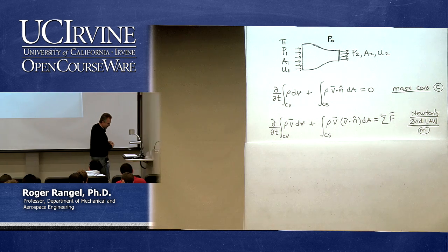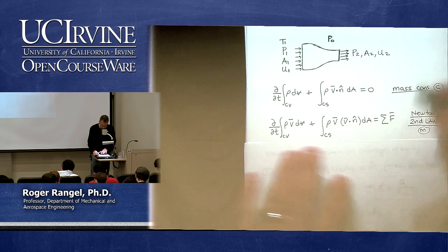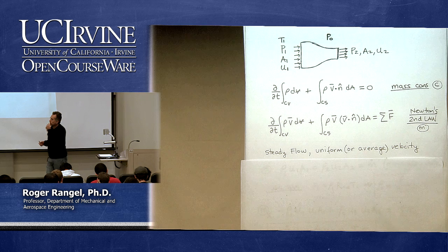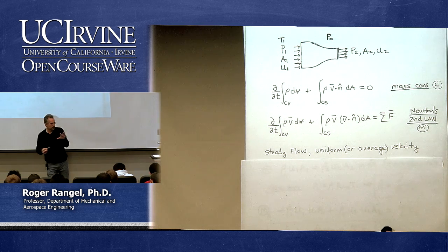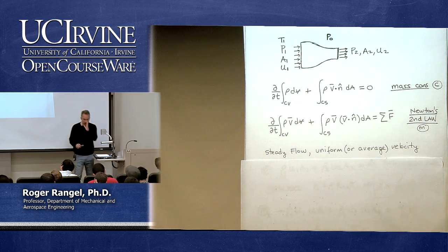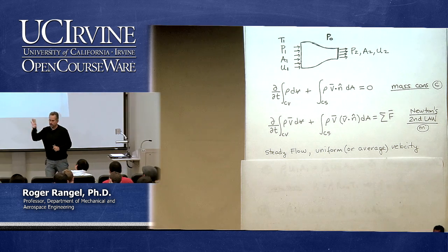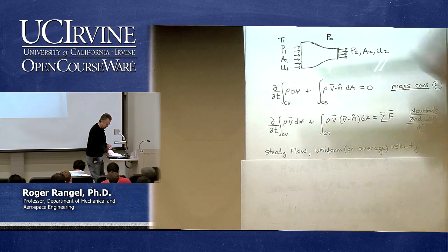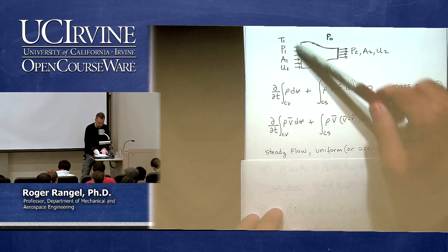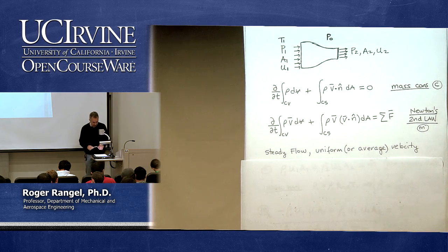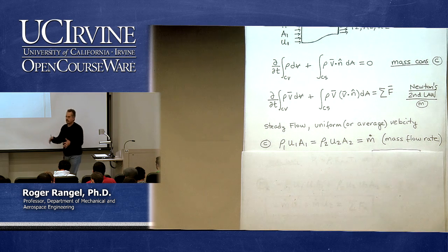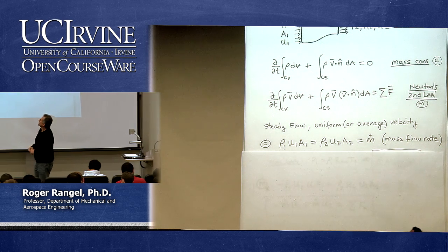And then I say, okay, what assumptions am I going to make? Precisely the ones that we just used in the derivation. So let's say it's a steady flow, the engine is running continuously. Take that the flow through the inlet and the outlet is uniform. That's already indicated in the diagram, for example, for the velocity, because you see that the velocity arrows here are uniform. And go ahead and simplify. So we just go through the same exercise that we did a moment ago.